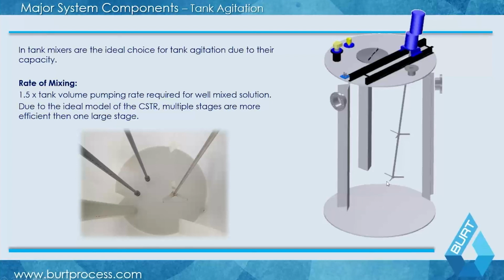This avoids what's referred to as short circuiting of the tank, whereby the waste could come in and basically go straight across without actually entering into that well-mixed solution. The reagent chemicals are also injected right into that mixer backwash as the waste comes in through the downpipe. Now, as a general rule of thumb,